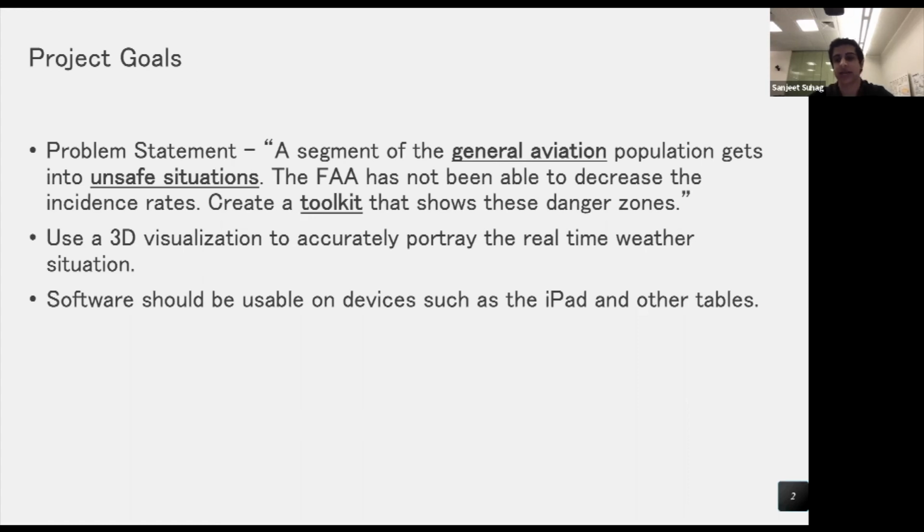In aviation, there are certain categories for weather conditions, and these are defined by the FAA. VFR, or visual flight rules, apply when a pilot operates an aircraft in weather conditions generally clear enough to allow the pilot to see where their aircraft is going. As opposed to that, IFR, or instrument flight rules, are conditions in which flight by simple outside visual reference is not safe, and flight has to be conducted by reference to your cockpit instruments, and navigation has to be done by electronic signals. So the aim here is to indicate where along a flight path a VFR pilot may be